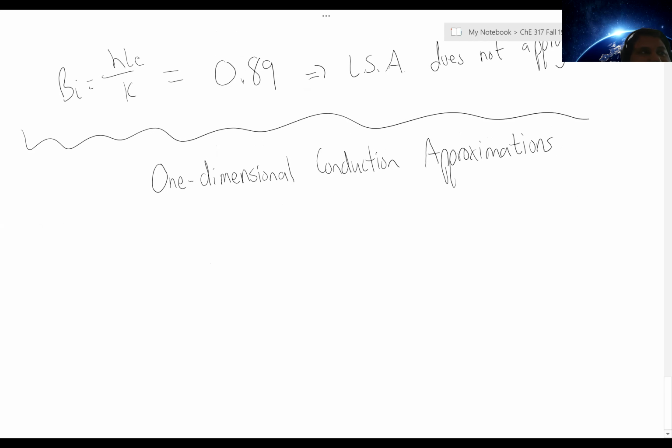If I consider an object or a slab of something, and I have heat transfer occurring from the sides, through application of symmetry I can simplify my expressions for heat transfer as a function of both position and time, primarily because I simply have to solve for one half of the system.